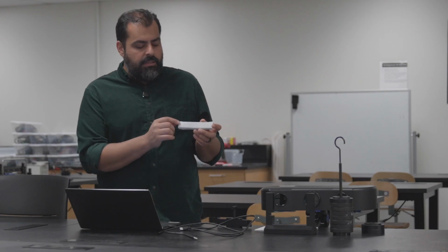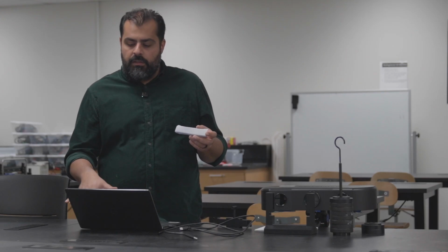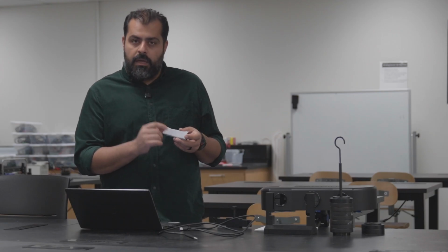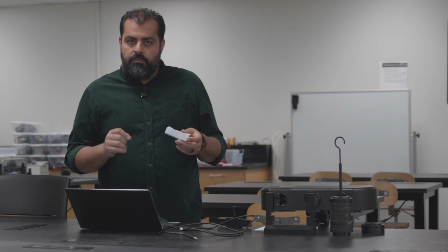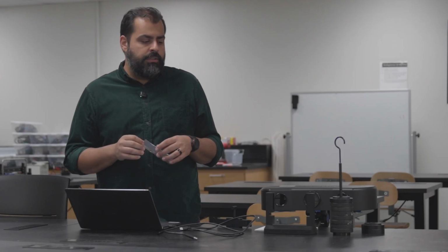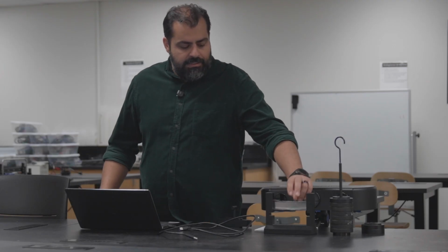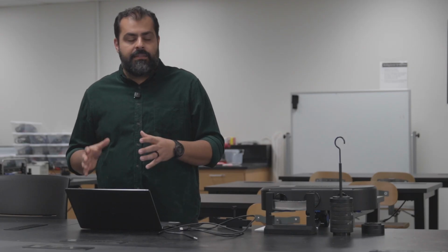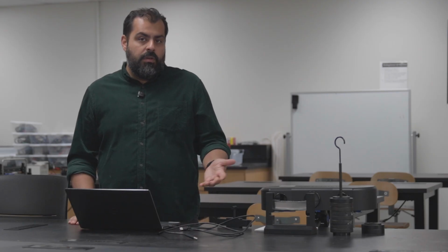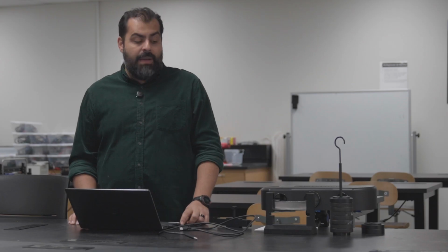So what happens is when you take the picture, the software, which is called VIC-3D or VIC-2D, is going to follow each of these points. And based on how each of these points is moving, it's going to tell you how much strain you see at a specific point, right? So that is how the sample works. So whatever sample you're working on, you need to make sure you actually create a speckle pattern. The samples we have in the lab are already prepared, so you don't really need to worry about that. But in future, if you're doing this for your research or you're doing this in a company, you have to make sure you actually create a speckle pattern, right?